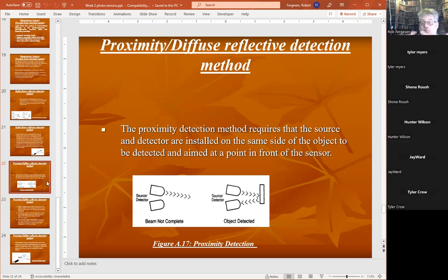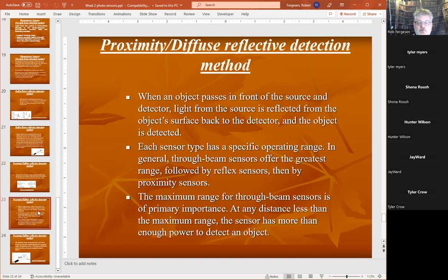If you can tune it, you can program your sensor to pick up only a certain color. It does that the same way as the reflective work, but using higher tech on the receiver side to know what the object is and judge, based on the wavelength and the intensity, whether it's a positive or not positive detection.